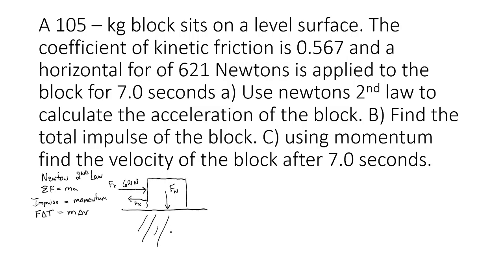And we have a coefficient of kinetic friction of 0.567. So if Newton's second law says force equals mass times acceleration, I know I have positive Fx minus Fk equals mass times acceleration.